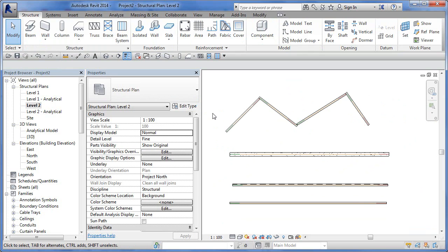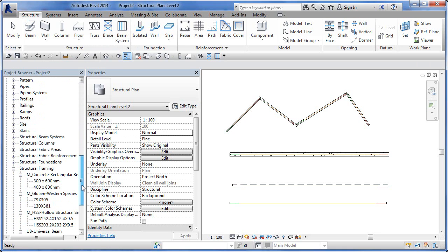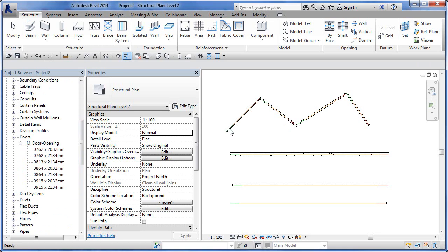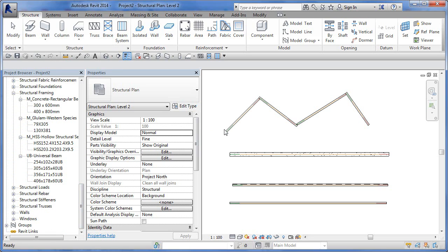When you want to load a beam, go into the structural framing, load it in. Once it's inside, you can start the beam tool here or up inside of here, or you can simply go down and navigate here anywhere in here. You can grab a door or window. You can go anywhere in the project browser and just kind of click on here and grab one of these guys and whoop, bring it out. If you bring a door out, you're going to have to pick a wall to put it in. If you drag a window in, okay, it's going to want a wall. Windows can't just float in space. Beams are different. They can just be there. They want to connect with other objects, which is worth pointing out.